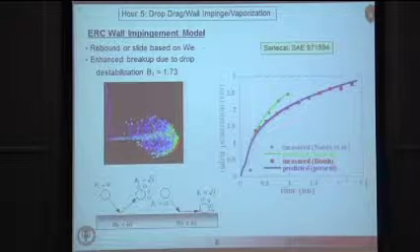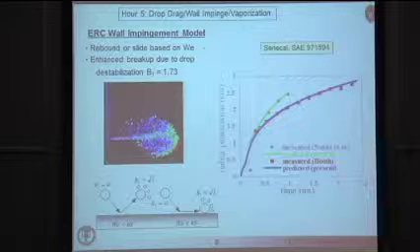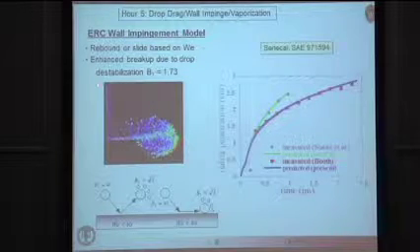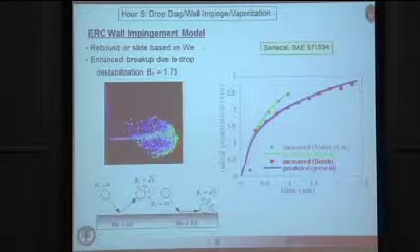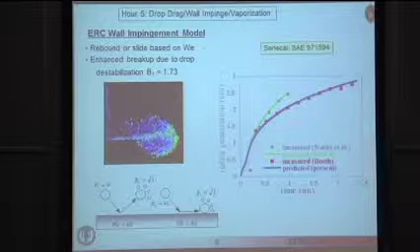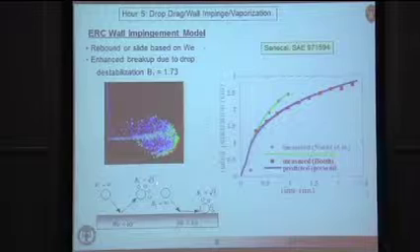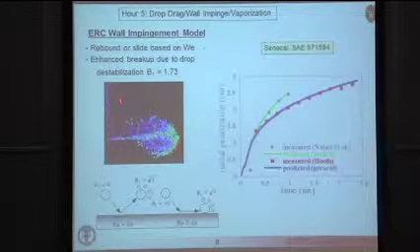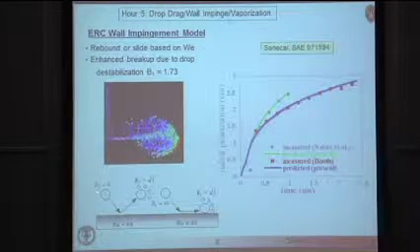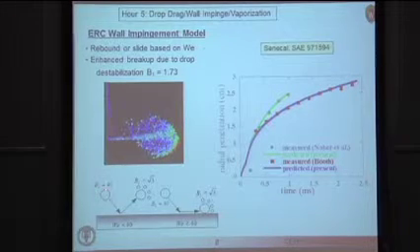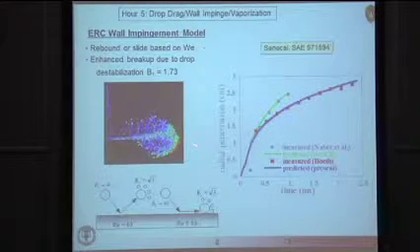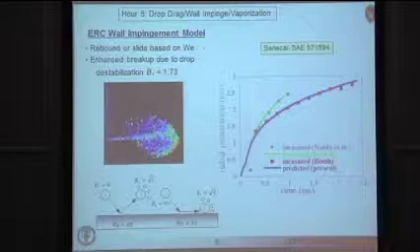In the case of the nozzle injection, it was cavitation processes in the nozzle. Here we have a huge disturbance being imposed on these droplets as they hit a surface and so on. And we found that we need to change the value of that constant that determines the breakup time when a droplet hits a surface. And that's how we're able to match data like you see here.